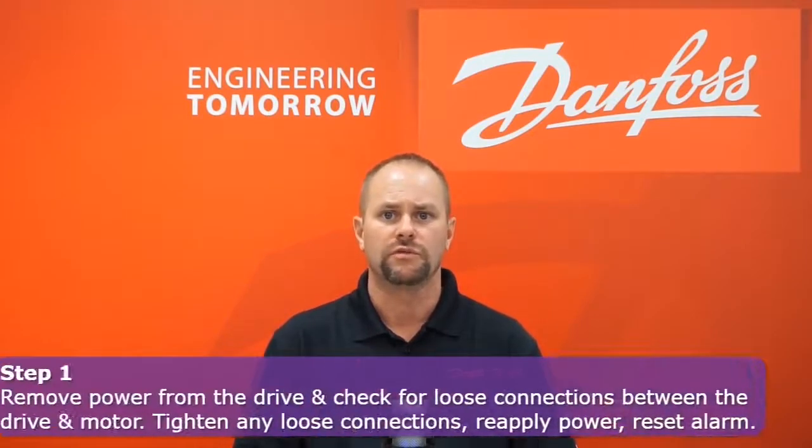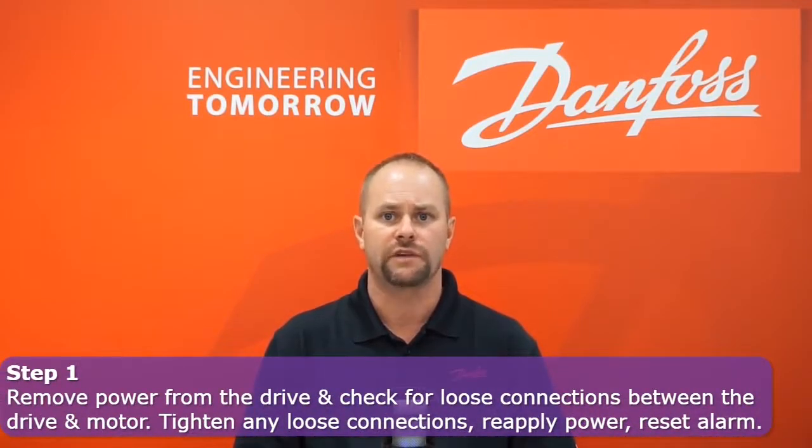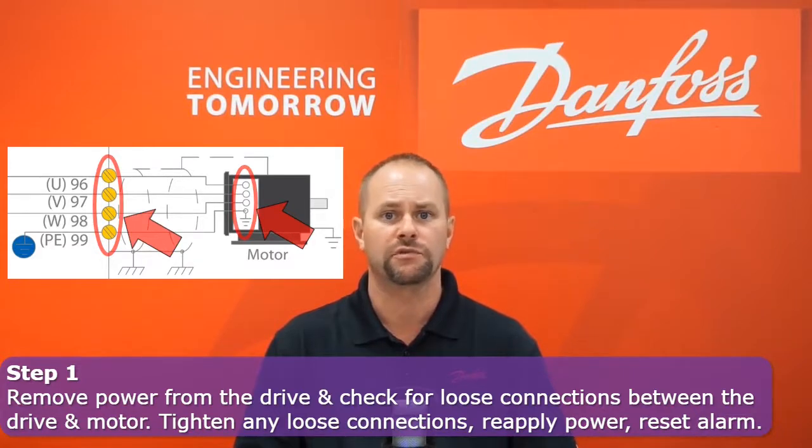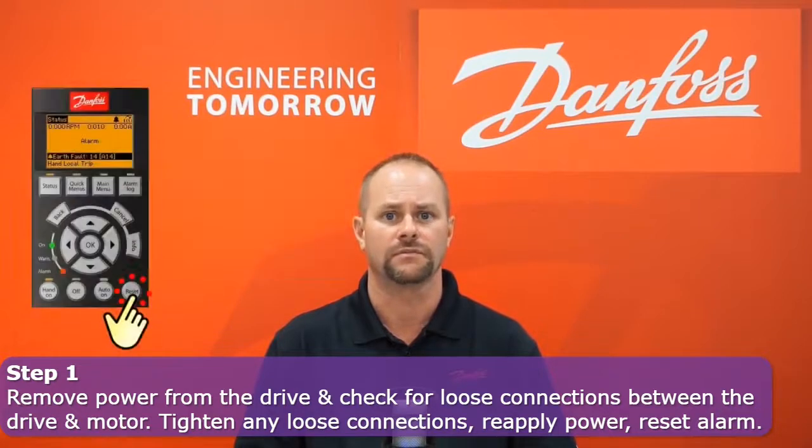Now that we understand what these alarms mean, we can follow some basic steps to assist in pinpointing the problem. The first step is to start simple. Remove all power from the drive and check for loose connections at the drive output terminals and the motor junction box. Loose connections can cause various problems and are responsible for a good share of these alarms. If you locate a loose connection, tighten the connection, cycle power to the drive, and attempt to reset the alarm.